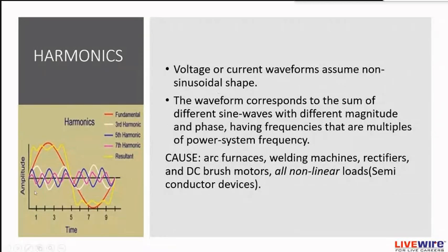You can see here in this picture, many frequency waveforms are presented here. All these together form the resultant waveform, that is the harmonic waveform. Collectively we can say the waveform corresponds to the sum of different sine waves with different magnitude and phase, having frequencies that are all multiples of the power system frequency. So that is the harmonics.